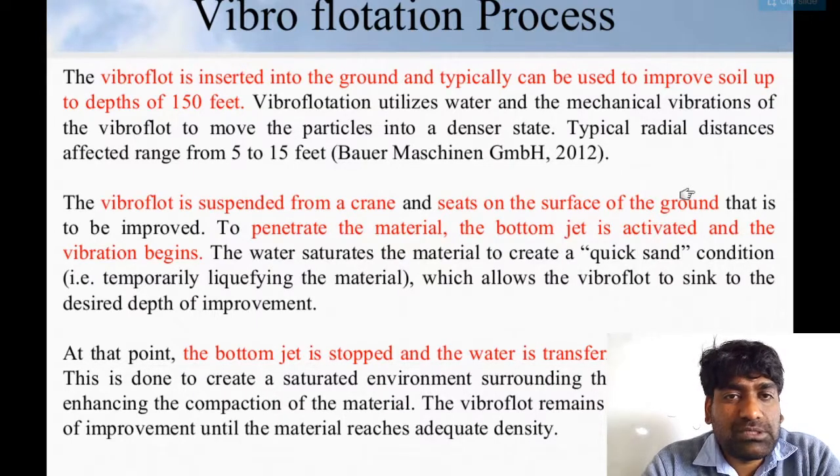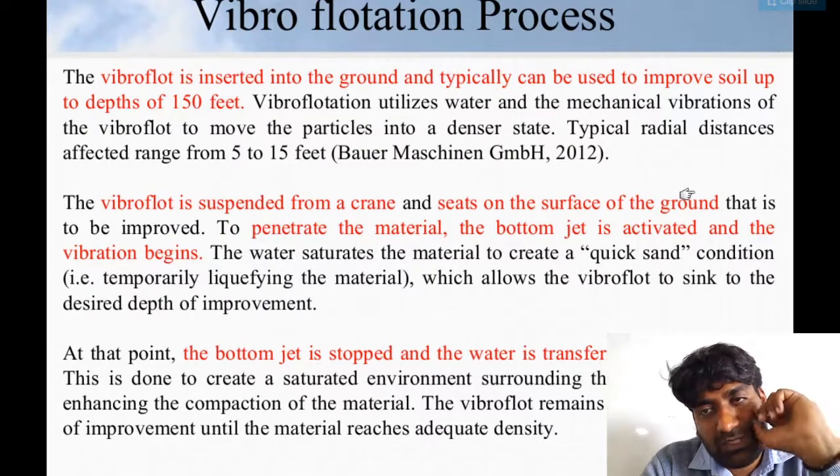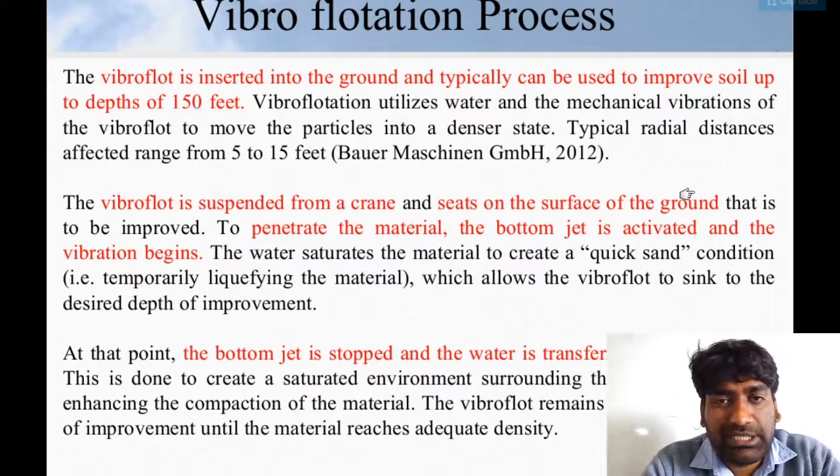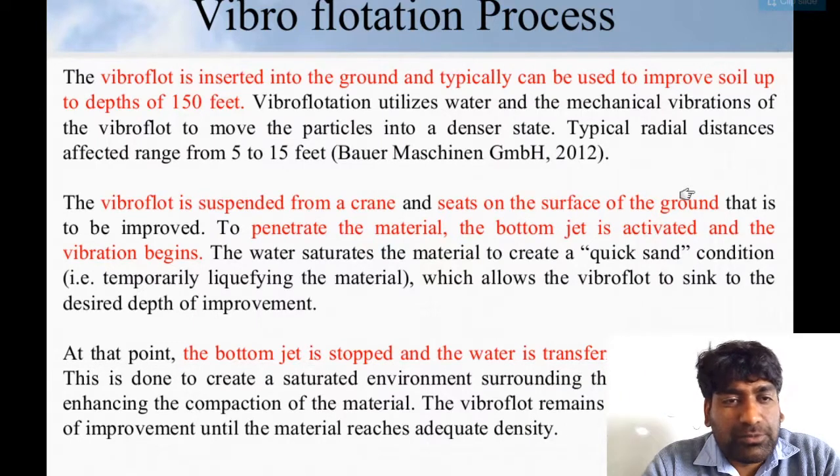The vibrofloat is suspended from a crane and sits on the surface of the ground that is to be improved. To penetrate the material, the bottom jet is activated and vibration begins. The water saturates the material to create a quicksand condition. You all might be knowing about this. Basically, the quicksand condition is temporarily liquefying the soil material, which allows the vibrofloat to sink to the desired depth of the improvement.